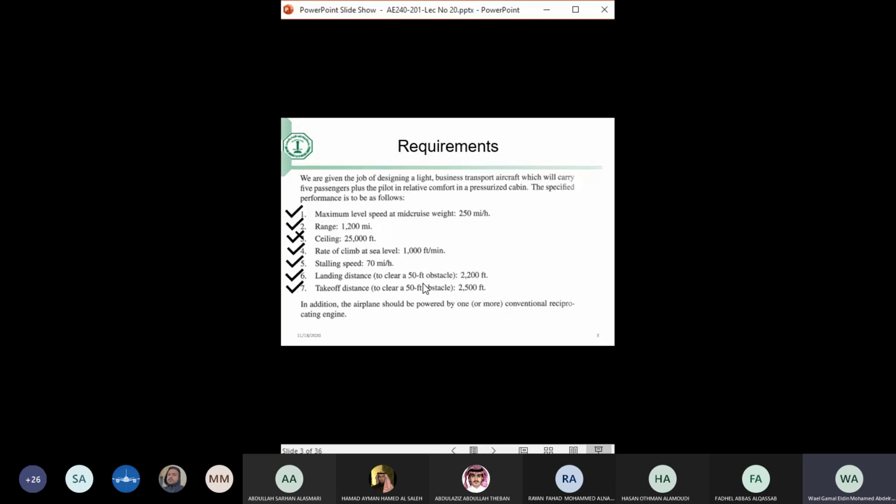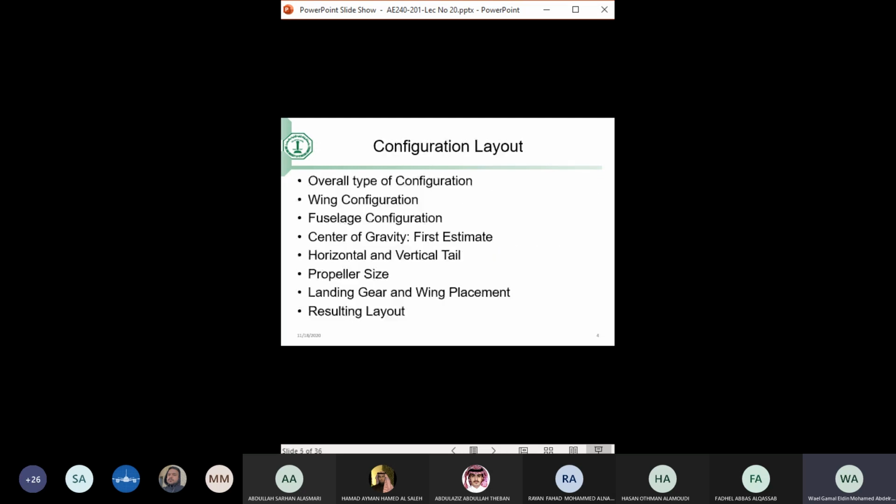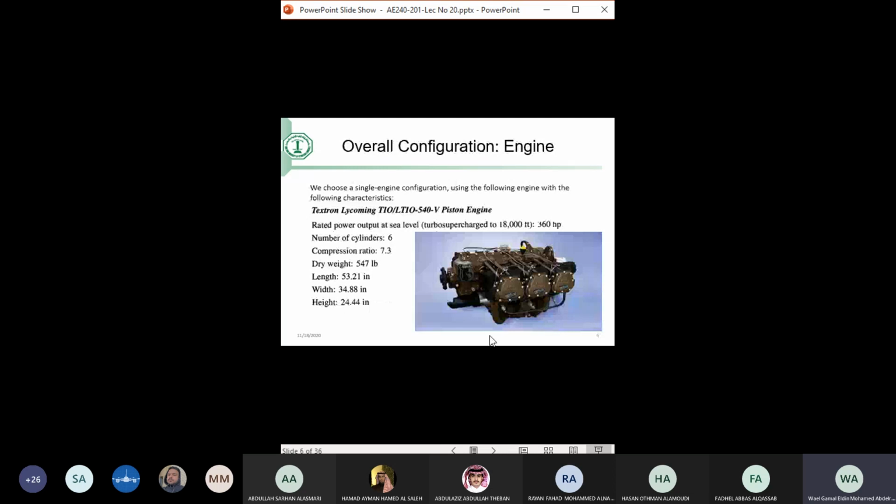So if I go to the rate of climb equation, I can see if I can make the 362 become 360 with a slight change in the aspect ratio: instead of 6.7, I can make it 7. That would be good, because the 6.7 that we put in there came from the assumption of K. If I change it slightly, I can get these 2 horsepower, and that will allow me to use this engine, which is lighter and less expensive than an engine that has 380 horsepower.